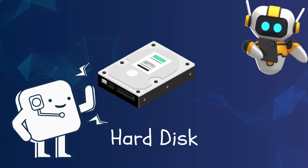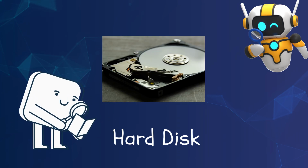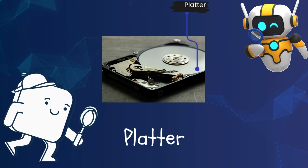A hard disk drive is a traditional data storage device used in computers and serves to store and retrieve digital information. It uses magnetic storage to record and retrieve data. Let's check the components inside the hard disk and see how it functions. Data is stored on the hard disk platter through the process of magnetic polarization, where magnetic regions on the platter surface represent binary data. The read write heads write data by generating magnetic fields and read data by sensing these magnetic fields. This technology allows hard disks to store large amounts of data efficiently and reliably.